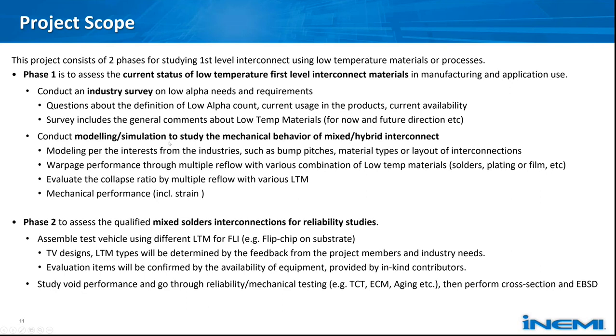Then in that phase, we will also in parallel, not necessarily in series, conduct simulation studies to characterize and understand mechanical behavior of these mixed geometries of low temp material interconnect. This modeling will be dependent on the feedback and inputs from the partners in this project from the industry, such as the scope for what bump pitches or the envelopes of the bump pitches to study, the types of materials, and the layout of the interconnect.